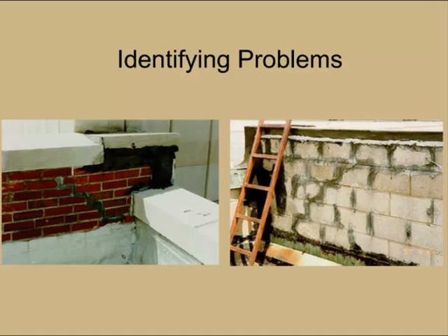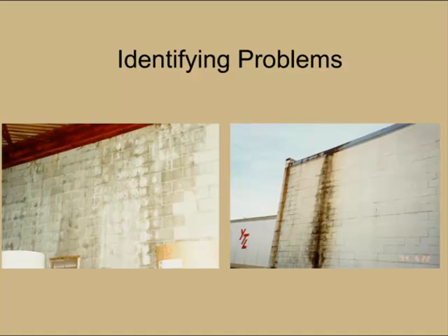Now, just looking at some examples here, consequences of neglect. These walls have been neglected, and when they went to make the repair, just so happens that they used the wrong materials. They used an asphalt roofing material or roofing cement to seal the cracks, suffocated the wall, created more harm than good, not effective. This here, I want to just touch on this real quick. This left-hand side, we're looking at the interior of a facility, but we see that white, chalky substance on the interior of that wall system, and that's efflorescence staining.